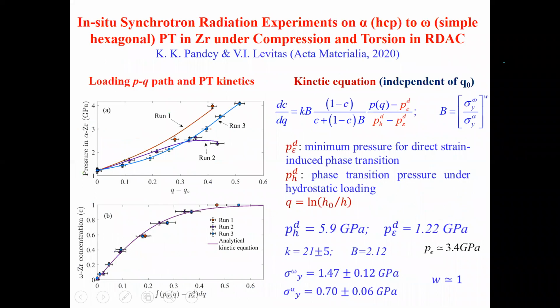But I would like to show our first quantitative confirmation. And actually, it took almost 15 years to get to this. Why? Because we cannot measure plastic strain distribution. That is why we could not use this equation directly, I mean, to calibrate, to check, but we use it in modeling. Well, now what we do, we are using the assumption that we have the same kinetic equation for any type of straining, be it plastic compression or any combination of pressure and shear. The kinetic equation is the same. This is a very strong assumption.